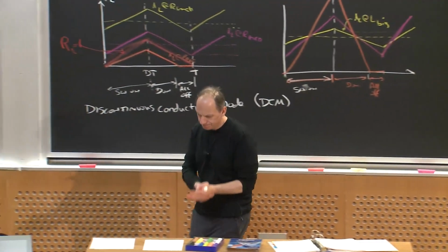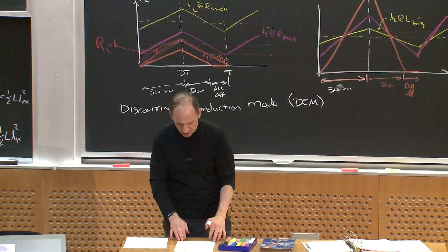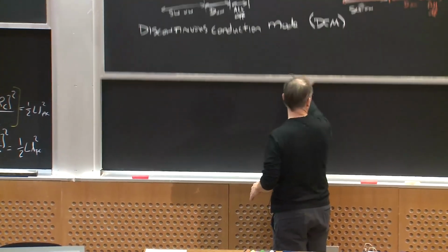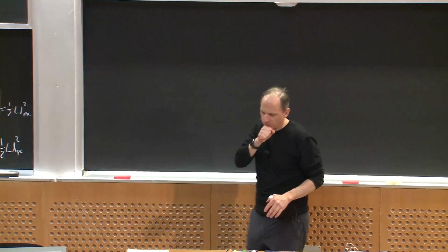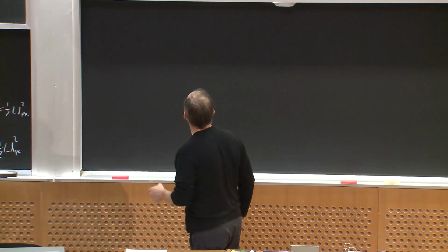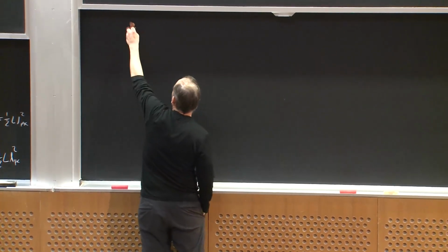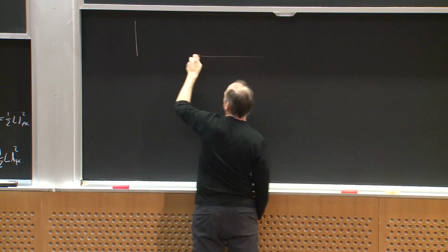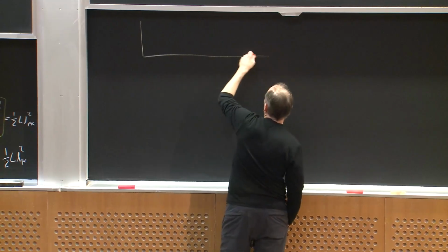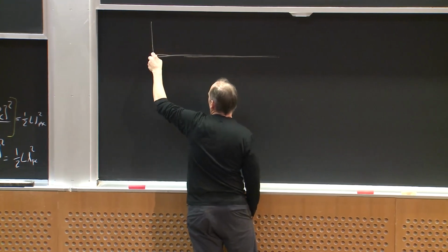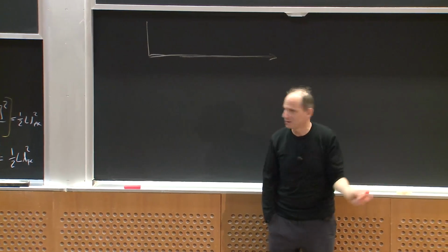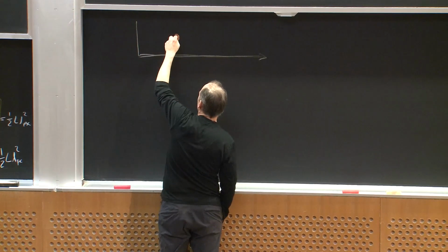Okay. So what can we say about operating in this new switch state? Let's think about that. What do our waveforms look like? Let's recreate our switching waveforms. We said we were going to have some duty ratio for our switch, and we were always focusing on the duty ratio of the switch. That's useful in CCM because the diode does exactly the opposite of what the switch does. But now, if we're going to talk about DCM, we can't talk about that.